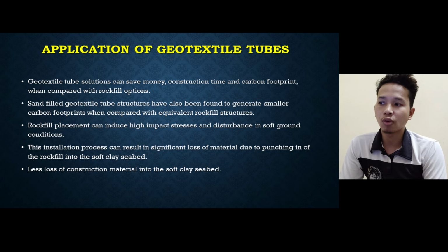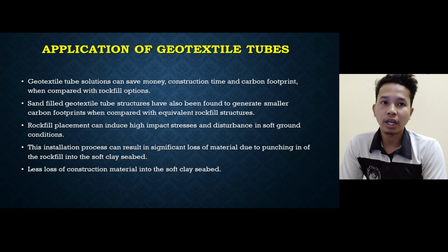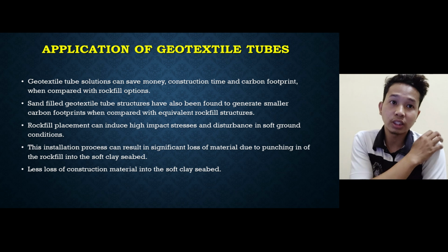Third, rock fill placement can induce high impact stress and disturbance in soft ground conditions. Fourth, this installation process can result in significant loss of material due to punching of the rock fill into the soft clay seabed. And lastly, there is less loss of construction material into the soft clay seabed.